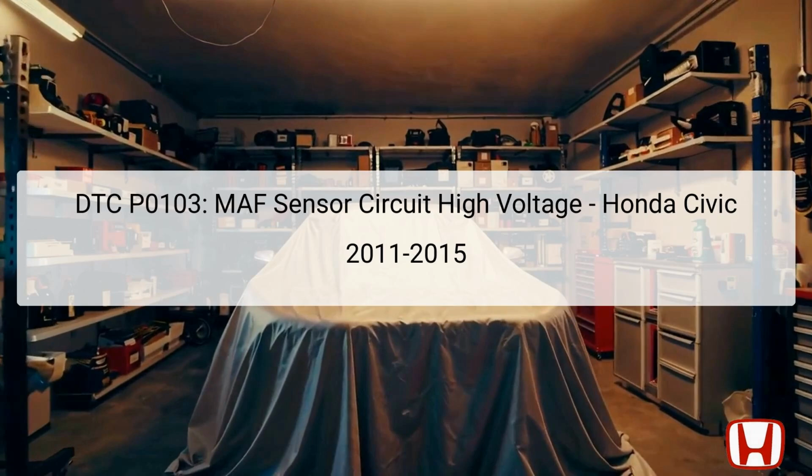The Diagnostic Trouble Code, DTC P0103, indicates a problem with the mass airflow MAF sensor circuit, specifically indicating high voltage. The MAF sensor is crucial in measuring the amount of air entering the engine, which is essential for maintaining the proper air-fuel mixture for efficient combustion.